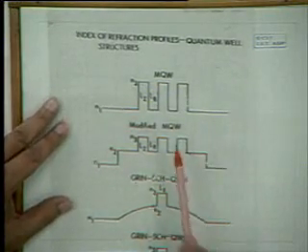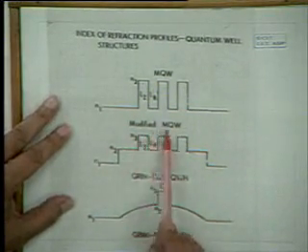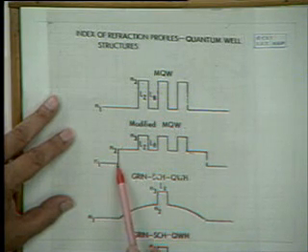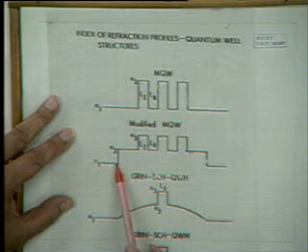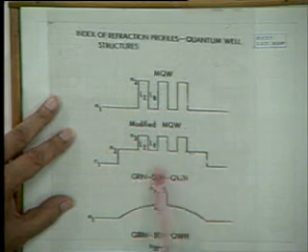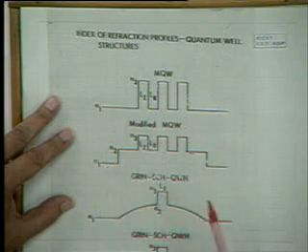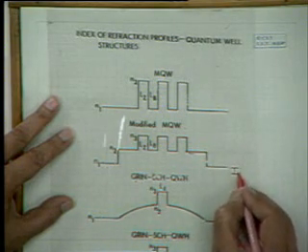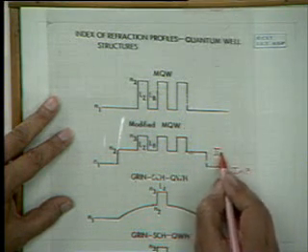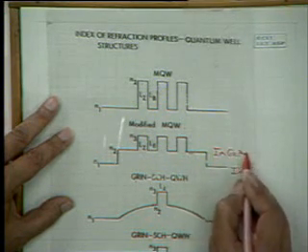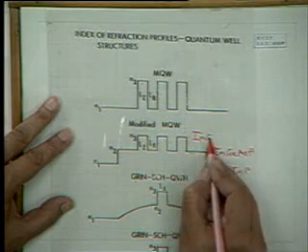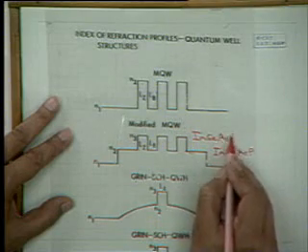How can you improve that? Well, you can have a modified multi-quantum well, in which you have the cladding, and then you can have steps. Typically, if this is indium phosphide, then this could be indium gallium arsenide phosphide of a particular composition, and then this could be indium gallium arsenide phosphide with a higher refractive index.